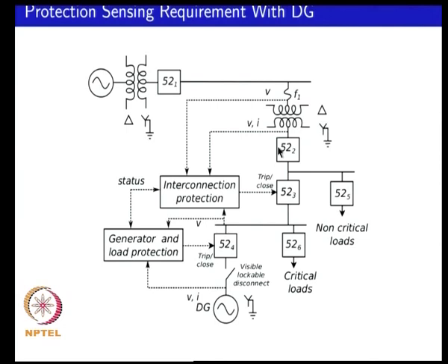You might have a 110 volt secondary PT, or you might have a 5 amp CT, where the actual information coming into the relay would be on a normalized scale rather than on a wider actual physical range. And so you need to have the adequate number of PTs and CTs at different locations.